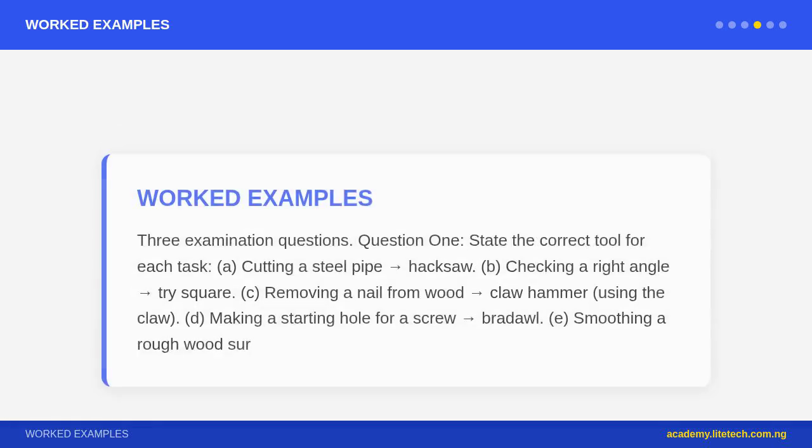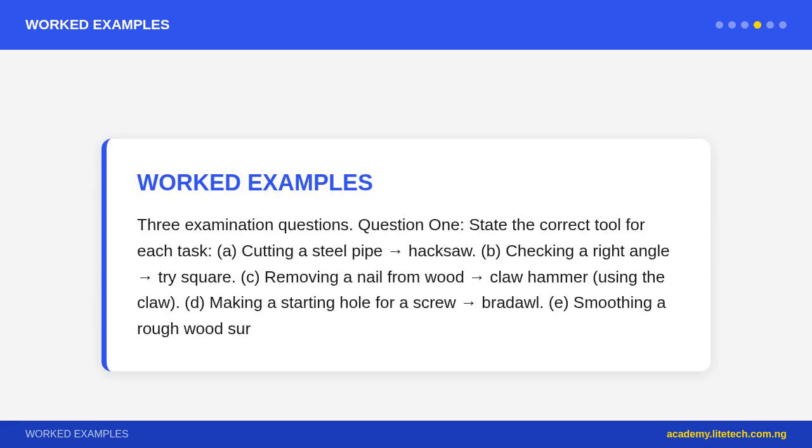Screwdriver, drives screws. Flat head, slotted, for straight slot screws. Phillips, cross head, plus, for cross slot screws. Pozidriv, similar to Phillips, slightly different design. Choose the correct size; a too small screwdriver slips and damages the screw head.